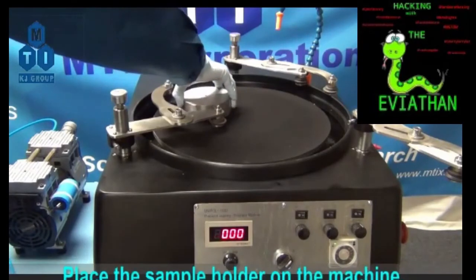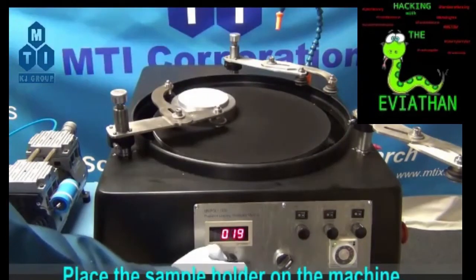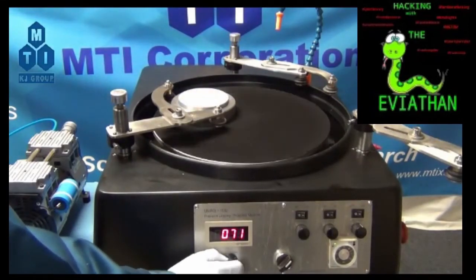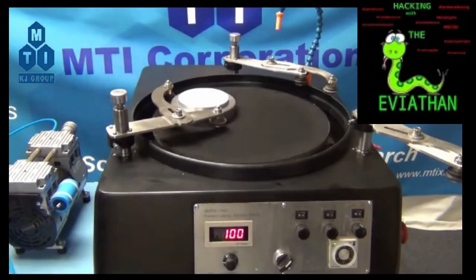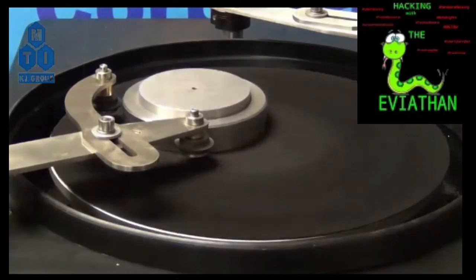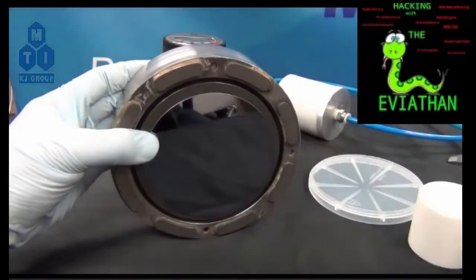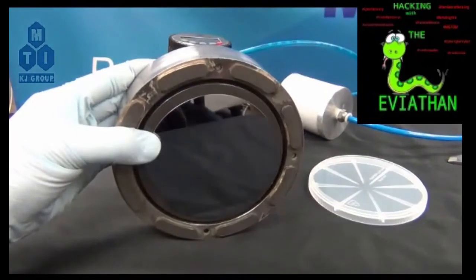Then a holder with the wafer samples downward is being put on and screwed in, and the rotation speed is being set in the interface. The rate can be calculated based on test wafers which have been fed through first and measured. Here is an entire wafer being polished with the special setup.